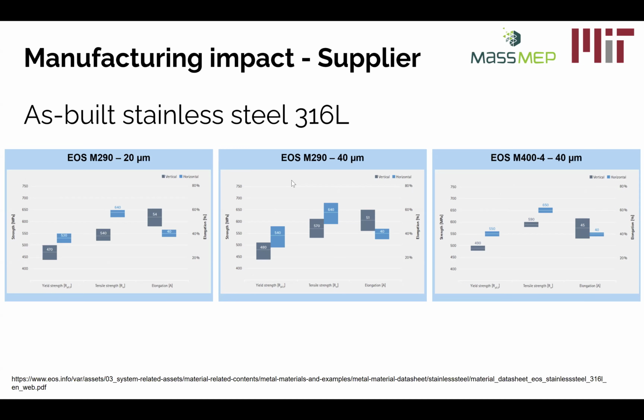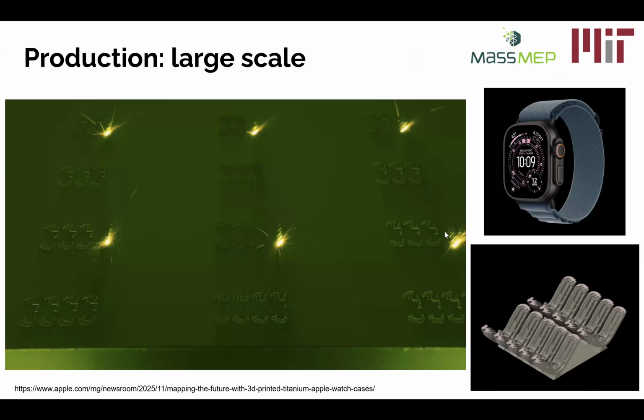There's a lot of nuance, and I'm not going to get into it, but basically how the laser strikes the powder bed and what that spot looks like affects your mechanical properties. And having more lasers, so you can control their positioning a little bit better because they don't have to cover the full build volume, affects the outcomes that you get. And that might be, I don't know for sure, one reason why we get a tighter distribution of mechanical performance. So the point I'm trying to make by rattling off all these details, I don't expect you to memorize them. It's just to say that every little thing matters from a component selection, from a process selection point of view. And that's why at the very beginning, I'll jump back through these 100 slides just to recap